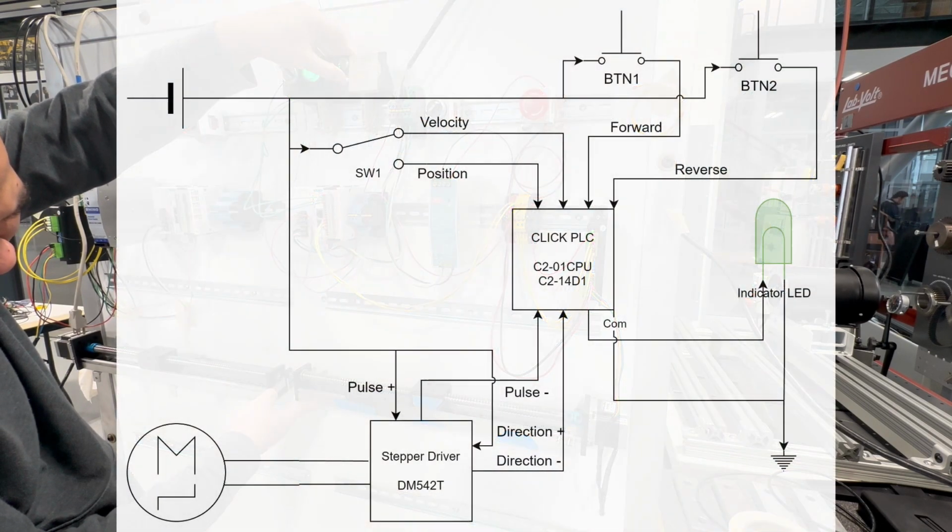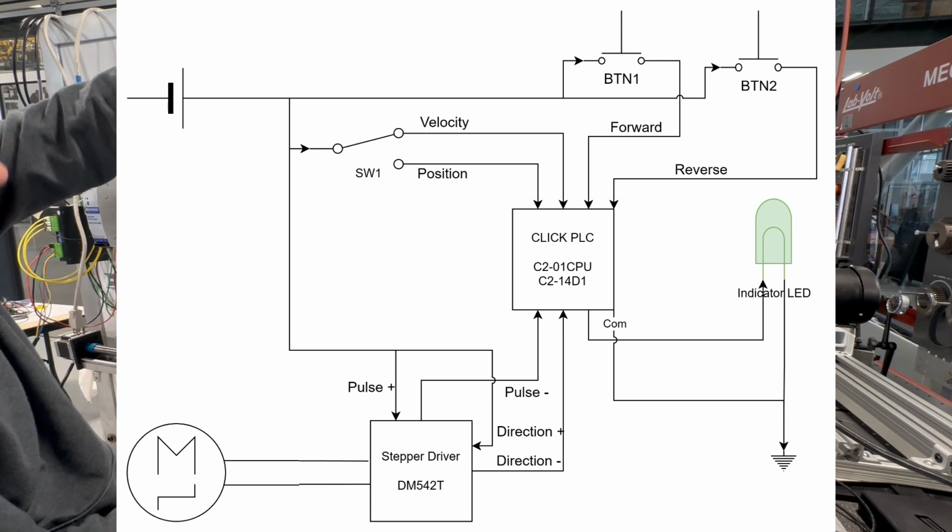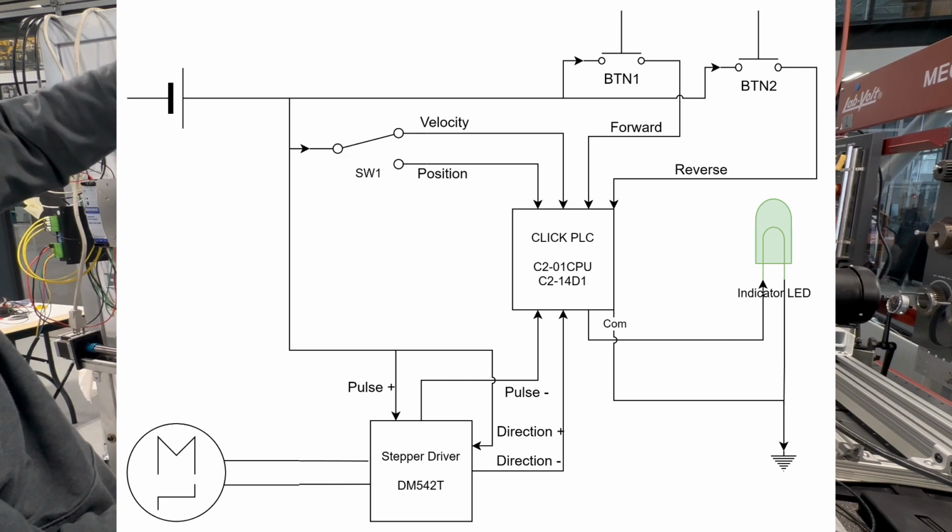Now take a look at the schematic for this lab. The PLC output is sinking, for those who are curious about the wiring between the PLC and the stepper driver.